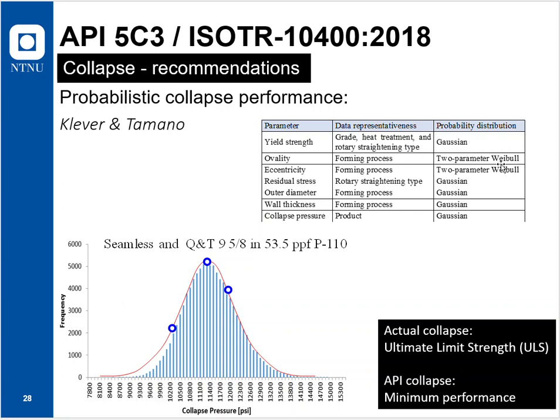It's a distribution of the ovality that is much wider than what you'll get for your pipe batch. You can put in your much more narrowed down, accurately measured parameters for each of these parameters. Ovality, for example, will be much more narrow than for the worldwide production, so the normal distribution would look much more narrow than this.